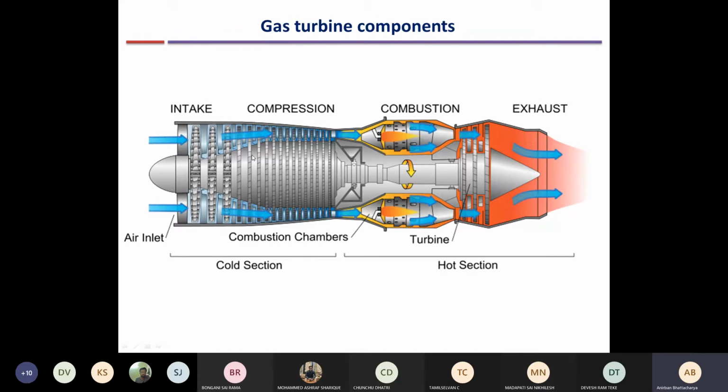And what is the minimum pressure after the turbines in the condenser? What is the minimum pressure in the cycle? What was the condenser pressure? 40 kPa. It can be 10 kPa, 20 kPa, means it is below atmospheric pressure, right? So if it is say 10 kPa and the maximum pressure in the boiler is 10 MPa, you can see that the pressure ratio is of the order of 1000. So for steam turbines, the pressure ratio is much higher.